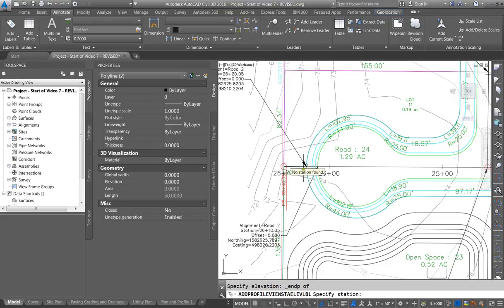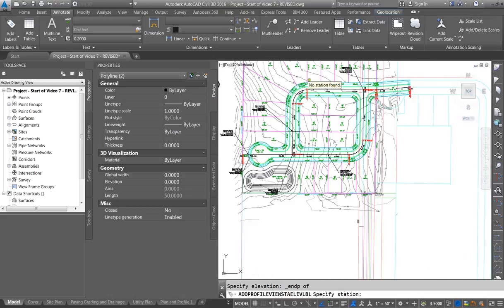But I want to bring it down as quickly as possible. Okay, so I'd like to see it go to almost natural ground. The reason I'm also going to natural ground is because, if I can follow the topography of the natural ground, because it's going high to low, then I don't have as much cut and fill. So these are the things that I'm thinking as I do this.